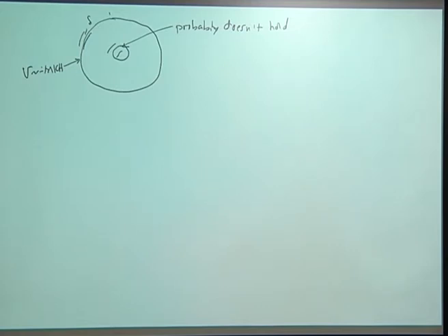So why is this important? Let's say you wanted to use this model to model a shrinking grain. I've been emphasizing this since the beginning: let's just choose this interface thickness delta to be the real interface thickness of a grain, 2 nanometers, 5 nanometers. I have 1 micron size grains. I have to put 6 mesh points in this little region delta. I'm dead. I can barely do 1 grain, much less a polycrystalline array.